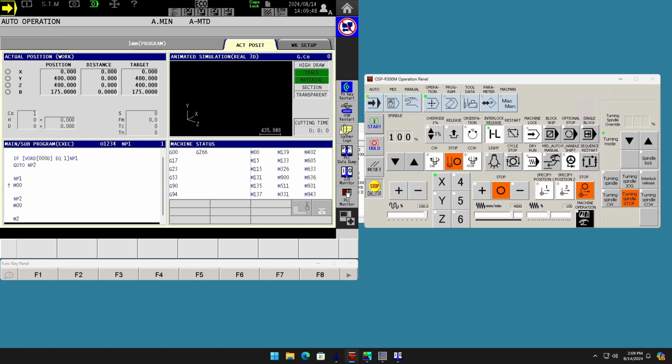All that they had to know was, okay, I've got tool 12 on the spindle, which just has to be a 1/2 inch drill. They put it in there, and then they hold interlock release and press cycle start. Everything after that's all managed by the machine.